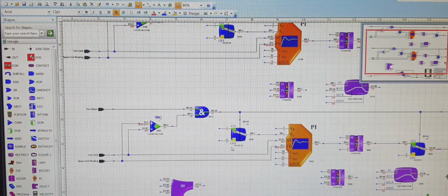We always have designed and maintained spaces and maintain the CO2 levels, the carbon dioxide levels in the spaces. Now, why this is important to understand is the measurement of elevated carbon dioxide levels in indoor air. They are an effective method of identifying poor ventilation in multi-occupant spaces. So we can find out if that building or that space is not being regulated properly, if its CO2 levels are higher, and if there's not enough proper airflow, circulation of air in that space or building.